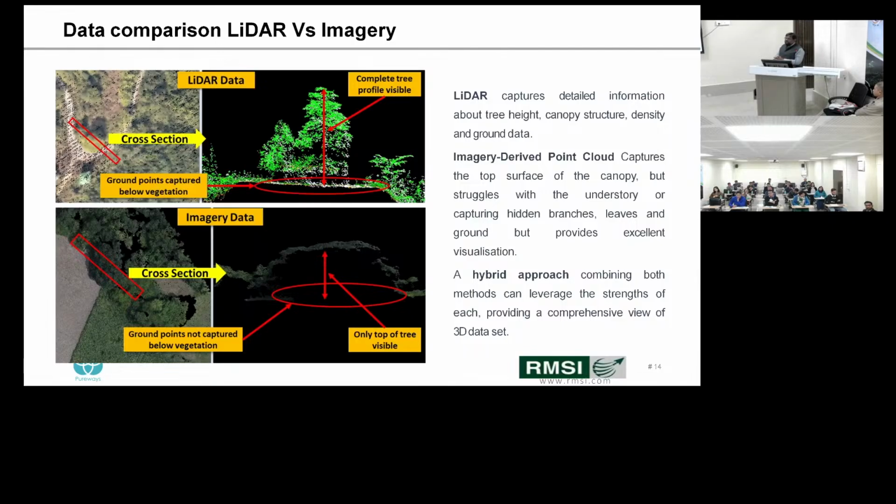In this project, even though it allowed us to do a photogrammetric survey, considering the importance of this project we decided to do the LiDAR survey, because this is a nationally important project and more data and accuracy are required. We were also happy to introduce LiDAR technology to the Brahmaputra Board so that future projects will also come with very accurate results. That's what we did, and we completed the entire data capture of 3,600 square kilometers of river basin.